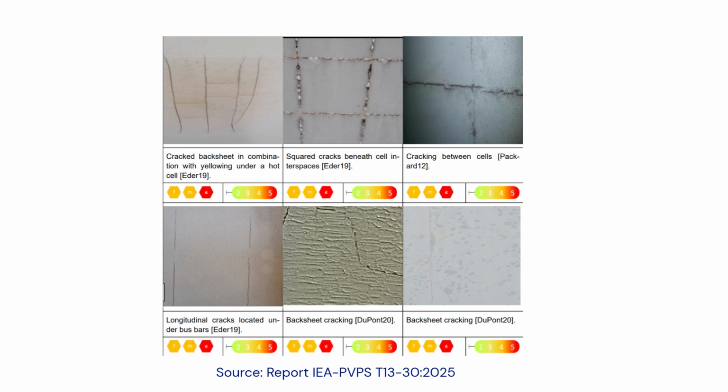The use of low-quality material, like low UV resistance, or incompatible material combinations between backsheet to encapsulant causes most of the premature degradation failures. Discoloration and strong chalking can be precursors for backsheet cracking. Deep cracks or bursted bubbles can be the result of local hotspots, burn marks that split or break the backsheet. A broken backsheet can cause electrical insulation failure, posing a safety hazard and a potential ground fault.